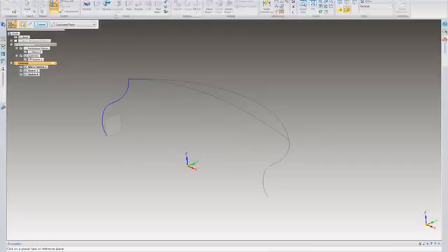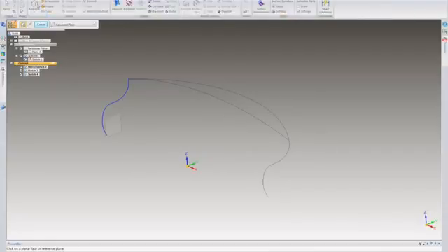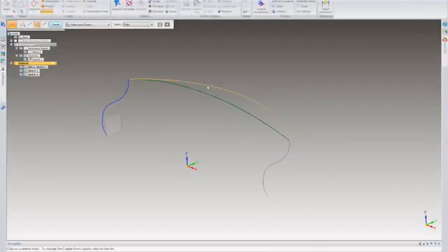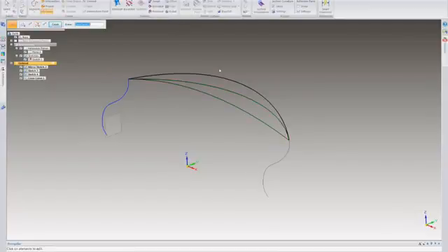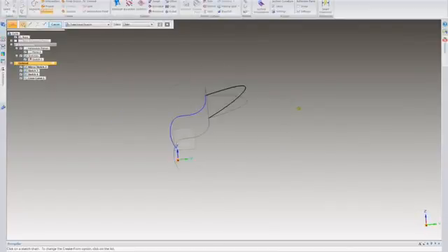All right, so now I have two sketches here. So basically, to create a cross curve in space is basically grabbing both of those geometries and telling it where they're going to meet. All right, so I'm going to say, you know what? I want to see where this guy and this other sketch would meet in space. So there's my third control point. So now I get a 3D curve.